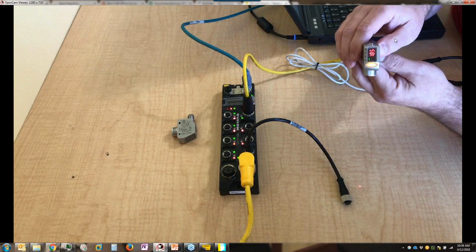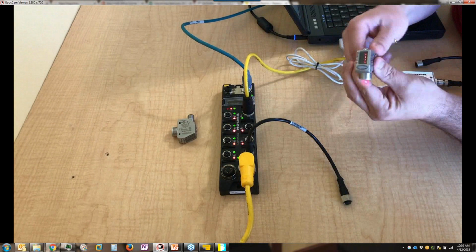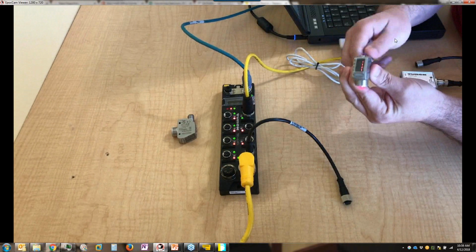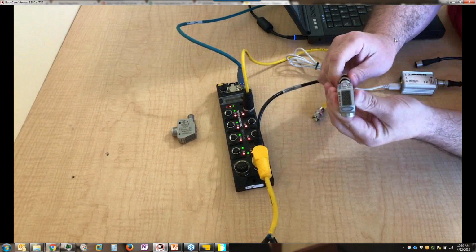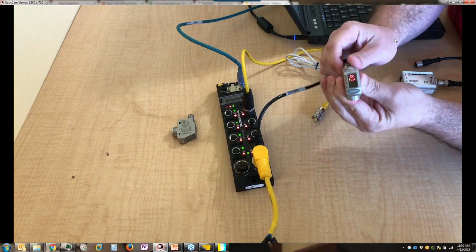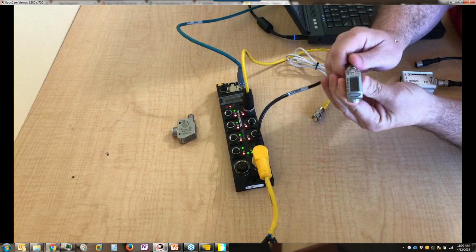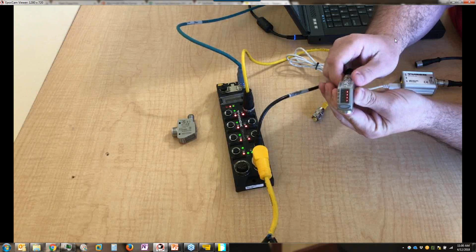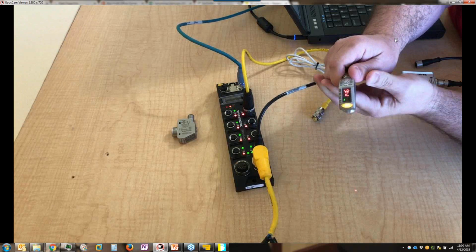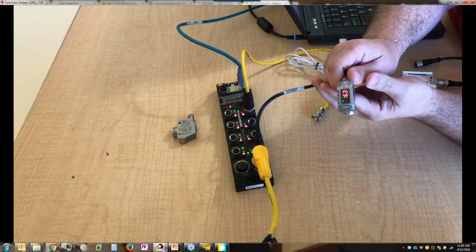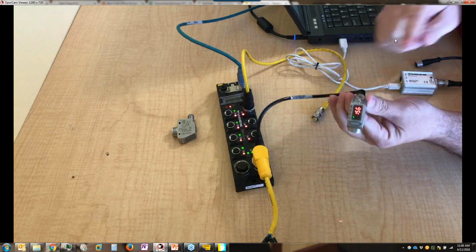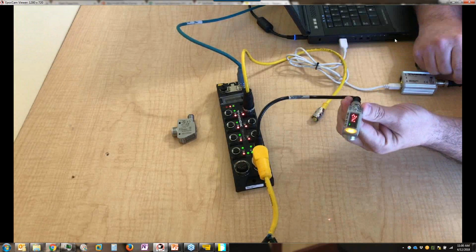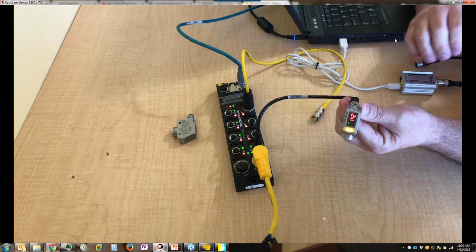Okay. I want to disconnect this from port 4 and put it back on port 1. So I am paying back Paul from Peter. And now this should read at 150. And it sure is. Illustrating the simple sensor replacement, which is the whole purpose of this webinar.